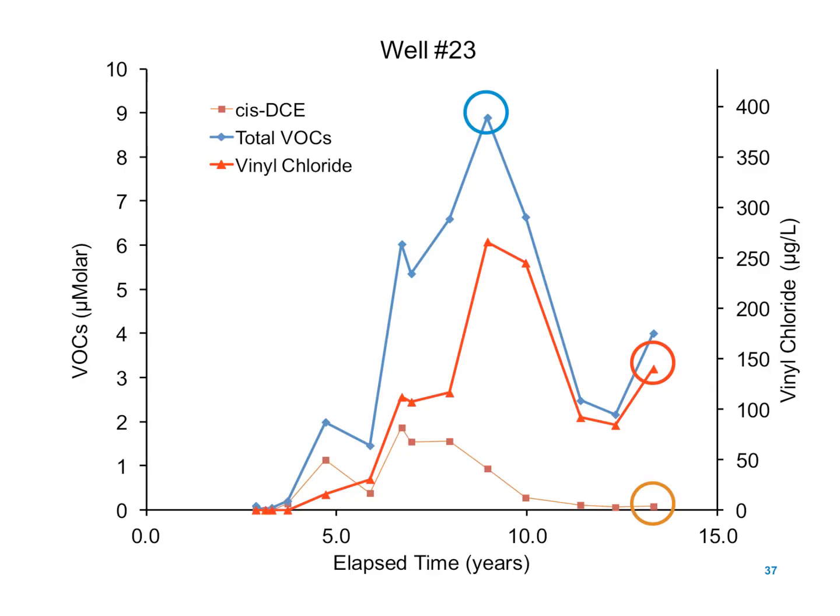To define C over C naught, I simply took the molar concentrations at the time the compound isotope analyses were collected and divided those by the highest concentration encountered at any time in the monitoring record. Now, it's a bounding value, but that's the best that we have from the data available. So C over C naught is what we are right now divided by the worst it ever was. Next slide.